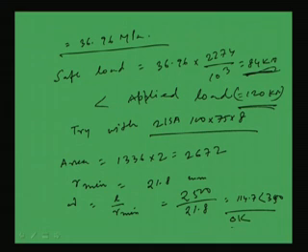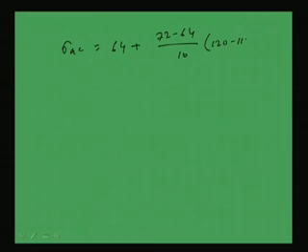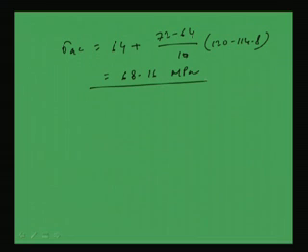So, from the slenderness point of view this is okay. Now, with this we can find out the sigma AC value from table 5.1 as 64 plus (72 minus 64) by 10 into (120 minus 114.8). After calculating we will get 68.16 MPa.